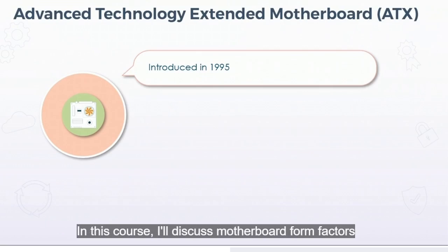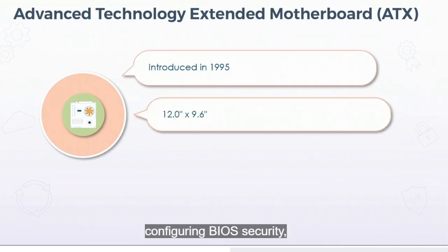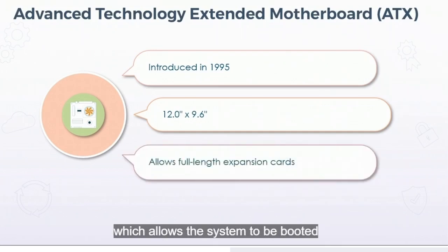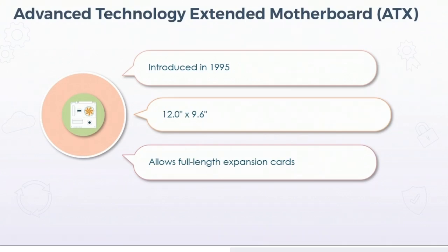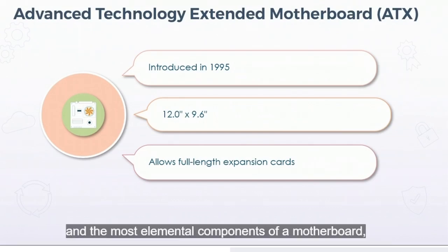Now, that didn't mean that every board had to be identical in terms of features and configuration, but they did have the same physical dimensions, which measured 12 inches high, or long, by 9.6 inches wide, or across, which was a larger size than many earlier models, which in turn allowed for many newer expansion cards that themselves were becoming longer, particularly video cards, which were starting to become much more advanced and as such needed more space for additional processing or even dedicated cooling.